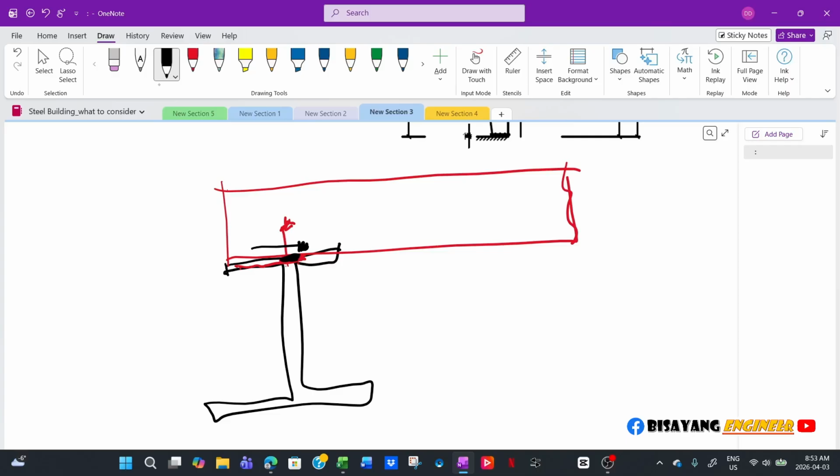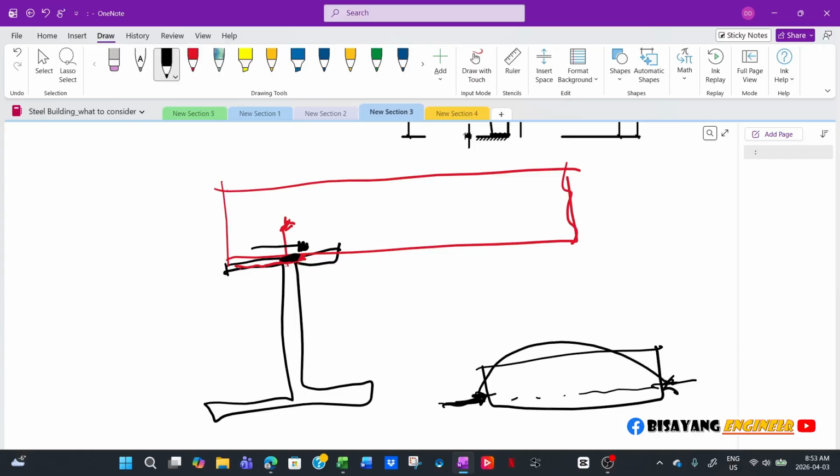It's the same as if you have a pre-stress girder, and then if you position the tendons at the bottom, this will bend upward, right? And then it will be countered by the weight. That's why it's ideal to have the tendons below the neutral axis so that it will create a bending upward and then counter the gravity load. So it's the same as this one.